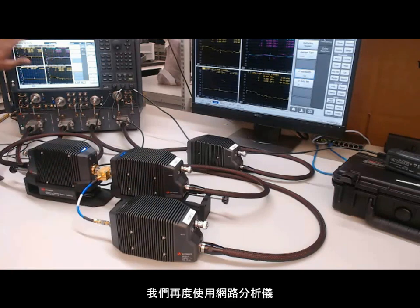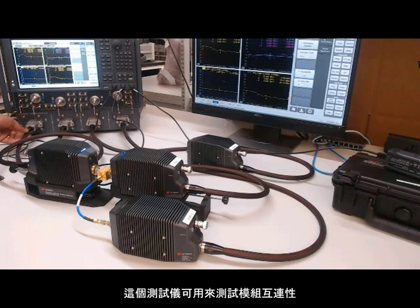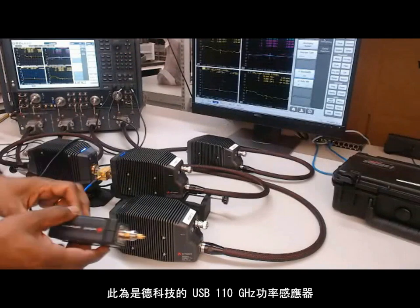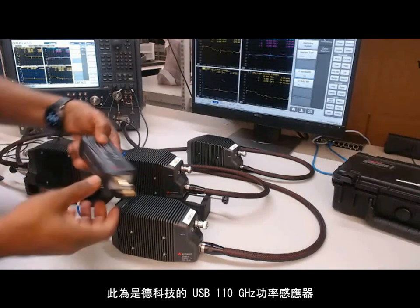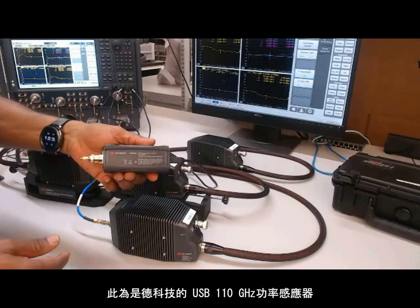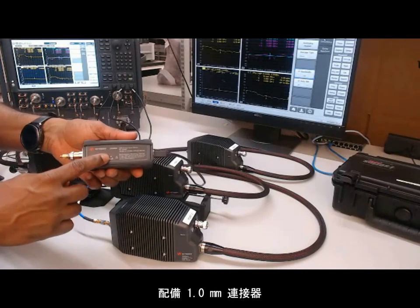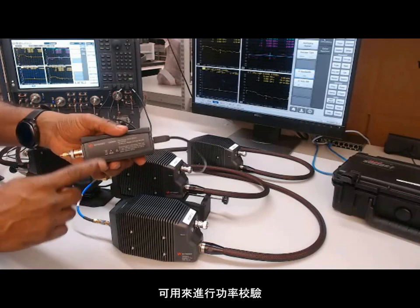Once again, we're using a network analyzer to do all the measurements, and a test set for the interconnection to the modules, as you can see. In addition, we need a power sensor, the Keysight USB 110 gigahertz power sensor. It has a 1 millimeter connector that will be used in the calibration for the power.